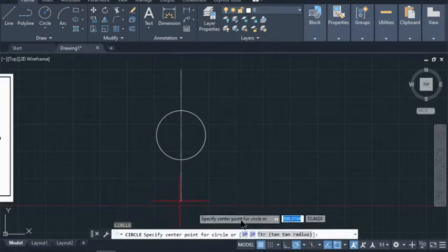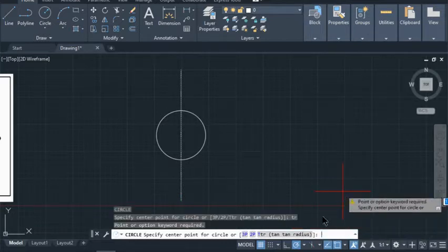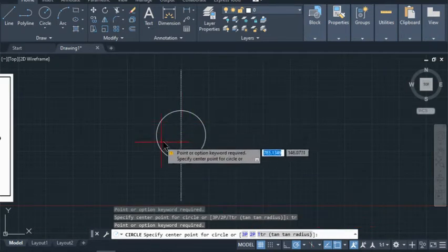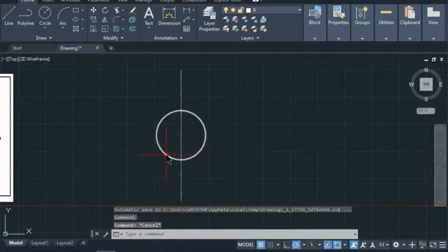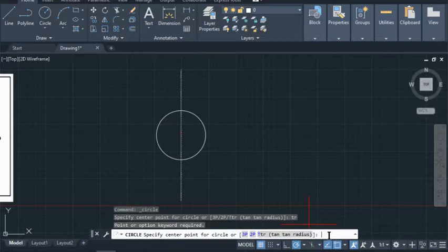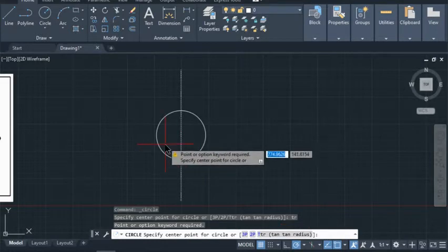See the circles show up, and then I'm going to do TR. There's something new here, guys. TR for tracking. So hit enter. And then they ask me, all right, let me try that again. Escape. All right, circle, and then select the center. I will be tracking. Point of selection is required.